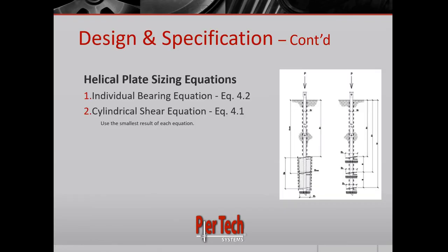Next, we have sizing helical bearing plates from a design standpoint. How does a pile really function once it's in the ground? How does it transfer load? Well, there's really two methods it's transferring the load into the soil. One is by plate end bearing. So that's the right side picture here, the individual bearing equation.